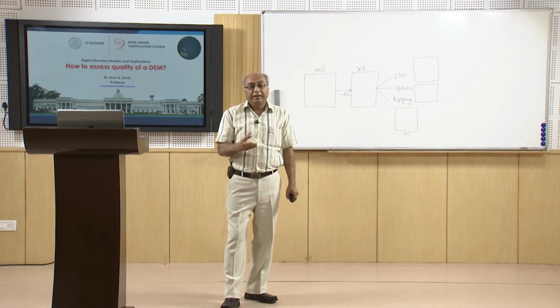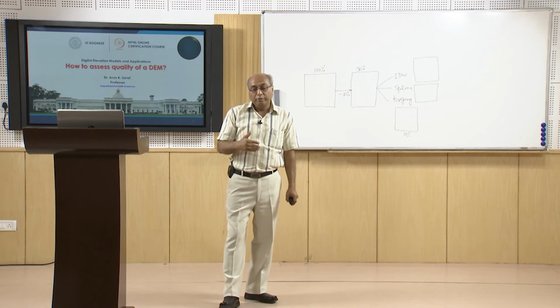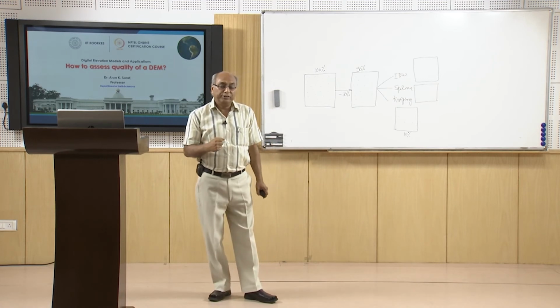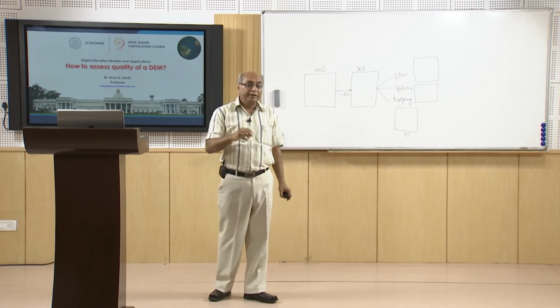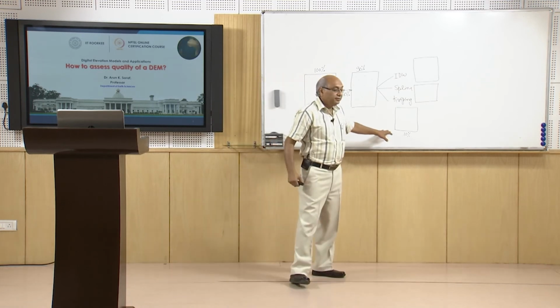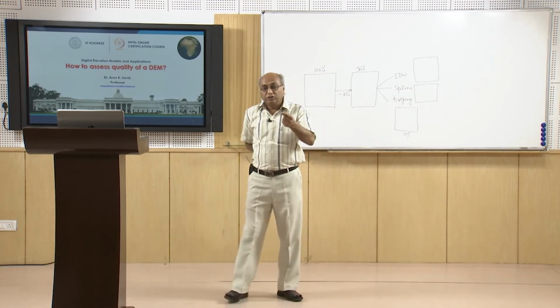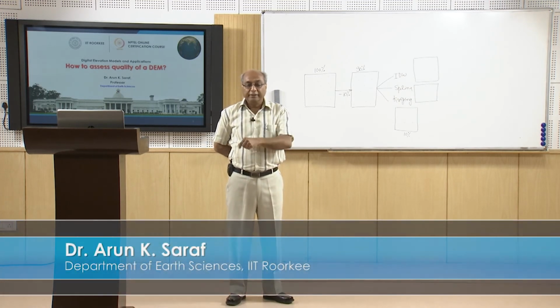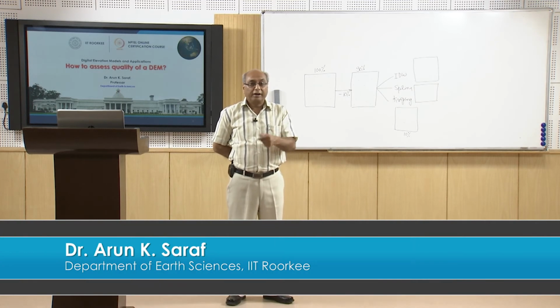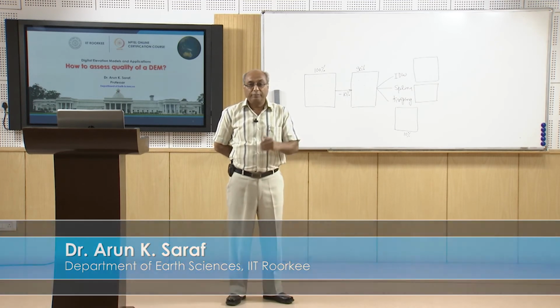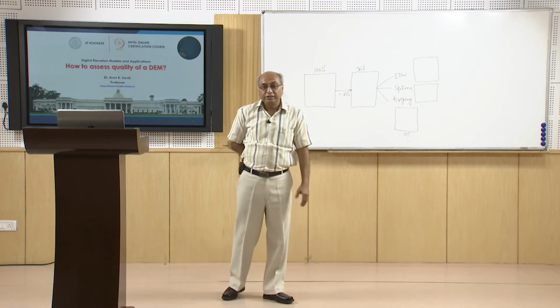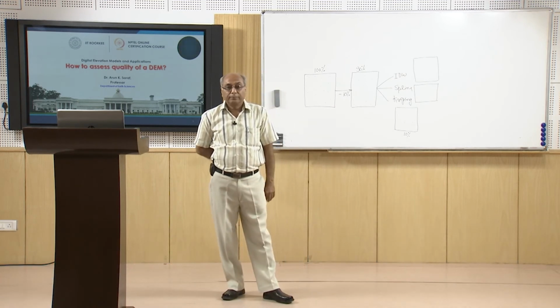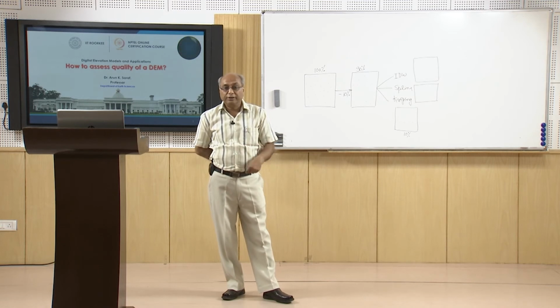If that set is available with us, the GCPs, ground control points, in which we have high reliability, we feel that they are more accurately collected elevation points, then we can put those points, as we did in this exercise, and check the corresponding elevation of the digital elevation model and how close the elevations of the digital elevation model are to these observations, which are coming either through differential GPS or some other survey techniques. By this, this exercise can be done.